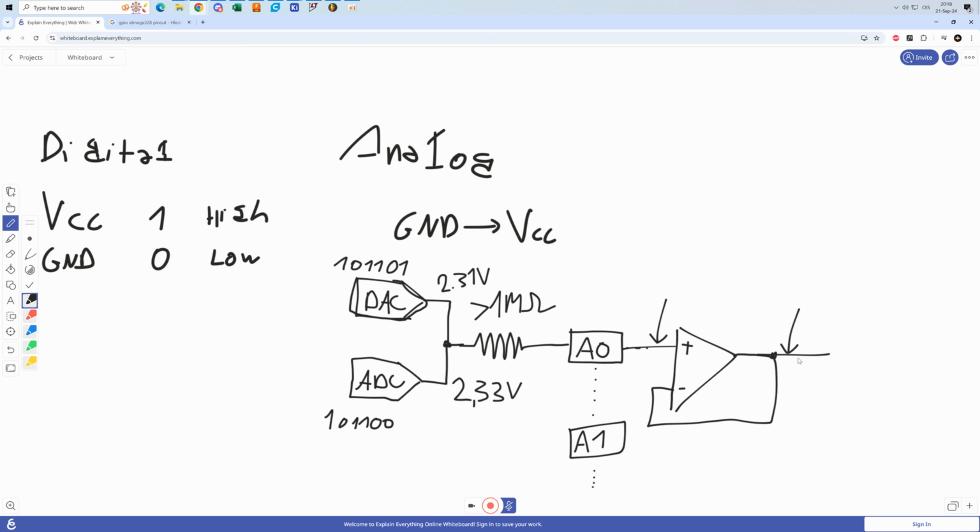However, it will be significantly boosted in the current. While this pin on itself had like 1 mega ohm impedance, this operational amplifier will have significantly lower impedance. It could be like tens or hundreds of ohms, which is enough to power some circuits that could be driven from this pin. Some microprocessors, as I said, basically have this buffer already integrated into the microprocessor. Some of those may not necessarily have to be activated. You may have to configure the pin to use the buffer or to disable the buffer.